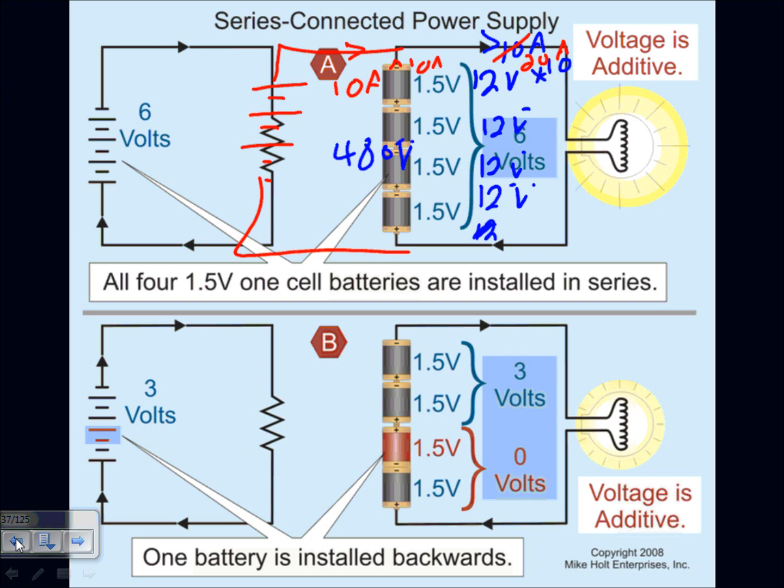We put batteries in series to add up to a certain voltage, because that's the voltage our equipment works at. You keep adding them to match your equipment. If your equipment works at 480, 600, whatever, you match your equipment. After that, at a certain amp, say 10 amps, 20 amps, every string will give you that. Now if I need more power, what do I do?